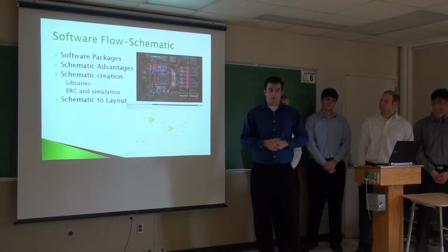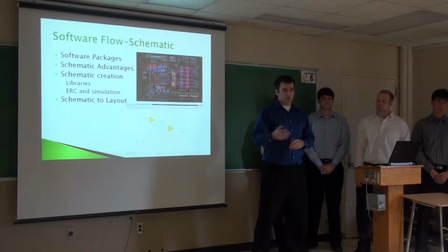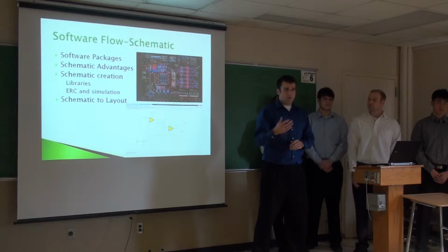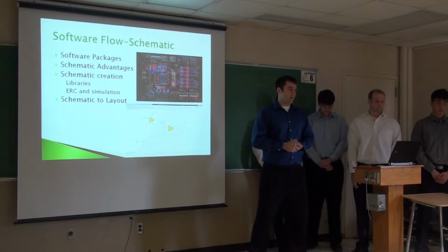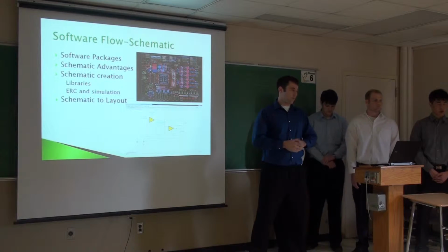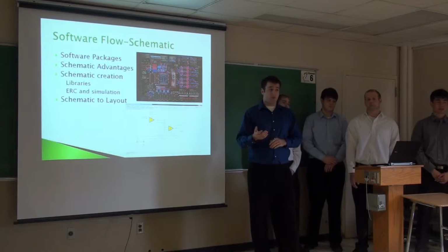And then schematic creation is pretty simple. There are a bunch of libraries in schematic editor software that will have your basic components and a lot of chips available. If the chips aren't in the libraries available, you can go on the internet and download libraries from different sites, like Texas Instruments will have a lot of libraries for their chips available. If those aren't available as well, you can create your own manually.